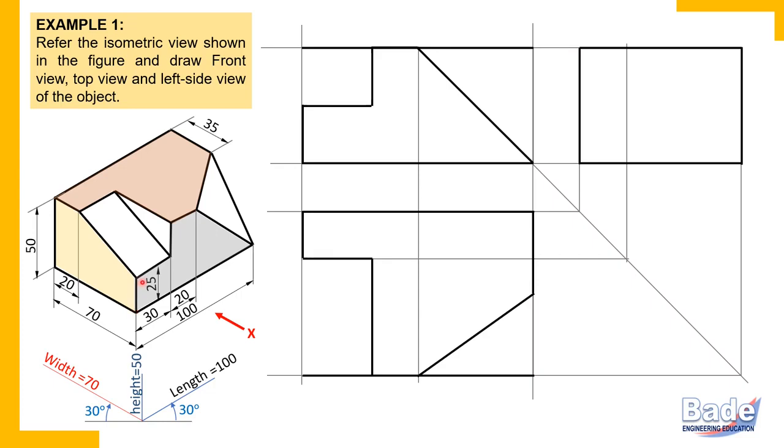Now we'll measure 25 millimeters on the front, this is the front side. From bottom, parallel to height, 25 millimeters vertically you should measure. You may measure independently. And here we have already measured 25 millimeters. Remember, this edge is common for these two surfaces. Since this surface is already completed, the 25 millimeter height we have already measured here. So you may project it in this manner. I prefer measuring 25 millimeters independently here. Okay. So we have drawn all principal edges and now this non-principal edge.